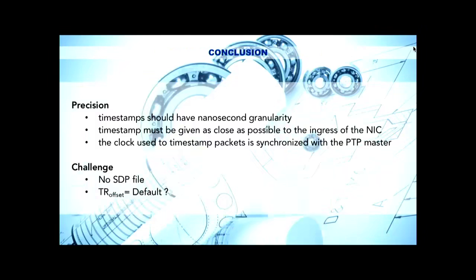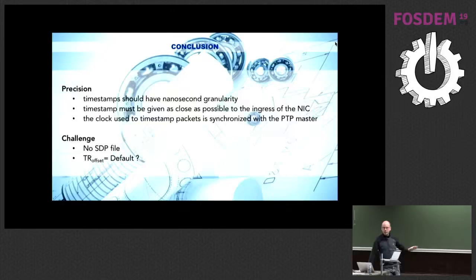So what did we see? Actually, for this application to work, we just need a precise timestamp with nanosecond granularity. And the timestamp must be given on a network interface card as close to the NIC, to the Ethernet jack, as possible. And of course, it needs to be synchronized with PTP.